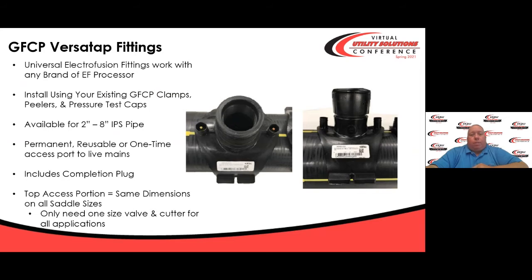First, the VersaTap fittings. I want everybody to know this is a universal electrofusion fitting. It's going to work with the same electrofusion processors you already use. This will install using your existing George Fisher brand clamps, peelers, and pressure test caps. The dimensions of the cap here are the same as a high volume tapping tee, so you can use all your high volume test caps. These fittings are available in 2 through 8-inch IPS. They provide a permanent, reusable, or one-time access point to live gas mains.